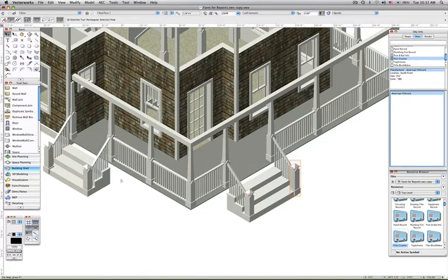I can then move over to another post and repeat the same thing, entering manufacturer's information, location, size, and color, knowing that this information is being tracked by the database within Vectorworks. I mentioned that the information can be input now or later. This is again part of the flexibility of Vectorworks. If you make a mistake or omission, no problem. You can edit the data at any time.